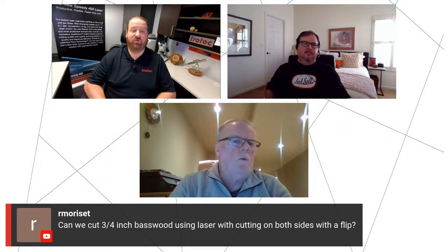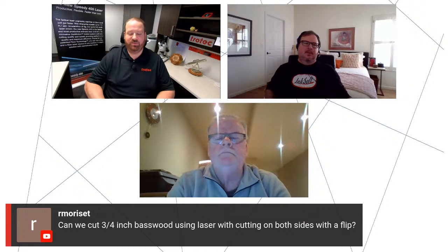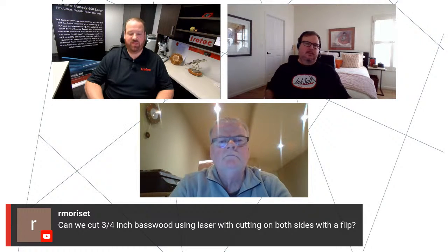So I would avoid it, or get a material that can be cut of that thickness, or a higher wattage that can get through that thickness from the front side. What about a different lens? It still won't help. No. The main issue in this case is not the lens; it's the fact that we're dealing with divergence issues through the thickness of a piece of material, or angle. It's like a magnifying glass in the sun, and so you're trying to flip it over and then accurately hit from both directions. It's just not going to happen. You're going to drive yourself crazy trying to figure it out. Long ago, I just realized it's futile and always cut from one side.